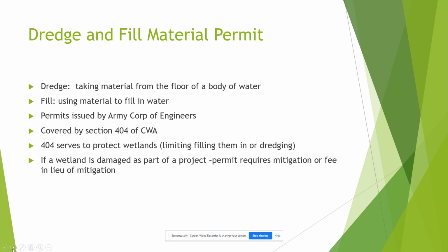But for waters of the United States, you have to go to the Army Corps of Engineers to get a permit. And it's covered by Section 404 of the Clean Water Act, which protects wetlands, so you're limiting filling them in or dredging.